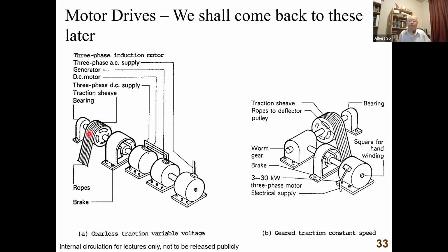And then because there's a contact between the rope and the groove, when the shaft rotates, by friction the ropes will be driven either clockwise or anti-clockwise. So it will lift the car up or let the car down. Okay, when the car is going down, you are lifting the other way up. So it's always lifting something. Either it lifts the car up or it lifts the counterweight up. If you lift the counterweight up, that is the car will go down.